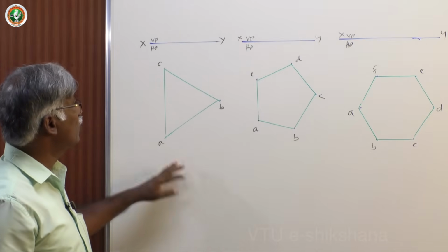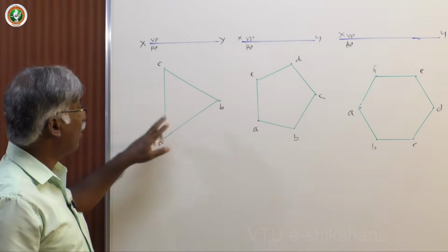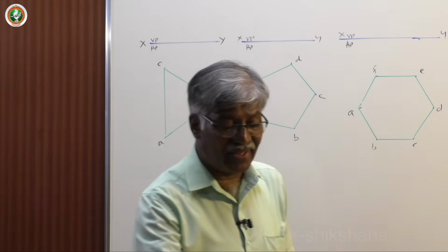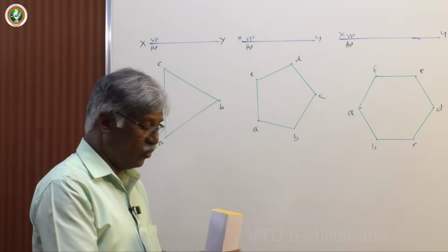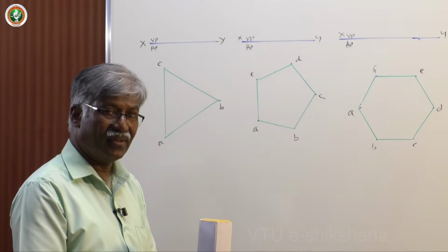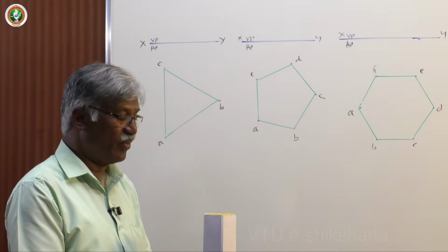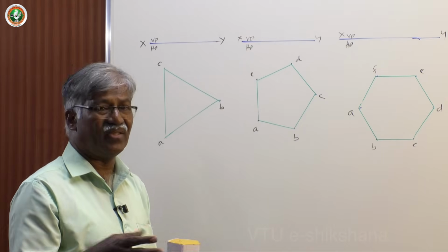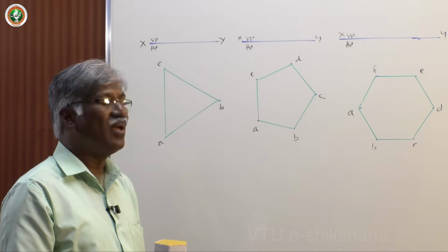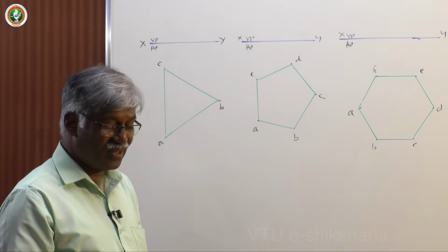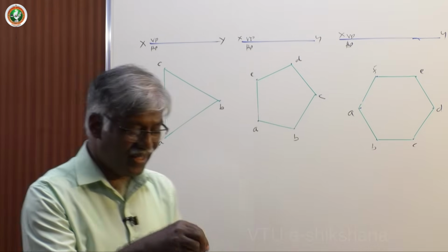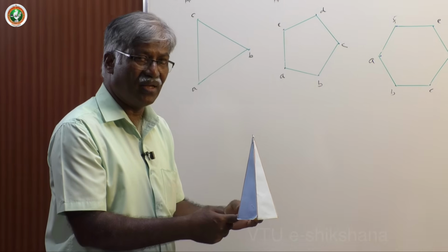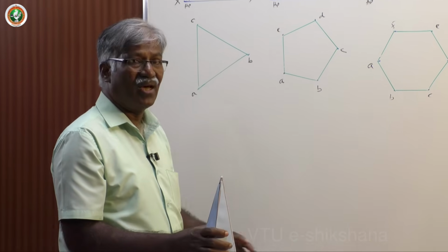I have drawn three figures with top view as reference. All lengths are true lengths here. Suppose that I have a pentagon with one base perpendicular to VP. Pentagonal prism perpendicular to VP. What is the top view? Top view is the cross section, that is pentagon. That's what you need. Height you can just fix in isometric. If you want, you can draw the front view also. Next comes if it is a pyramid. Again, the base of the pyramid is a pentagon, and one of its base sides is perpendicular to VP. This is enough for us to draw the isometric projection.